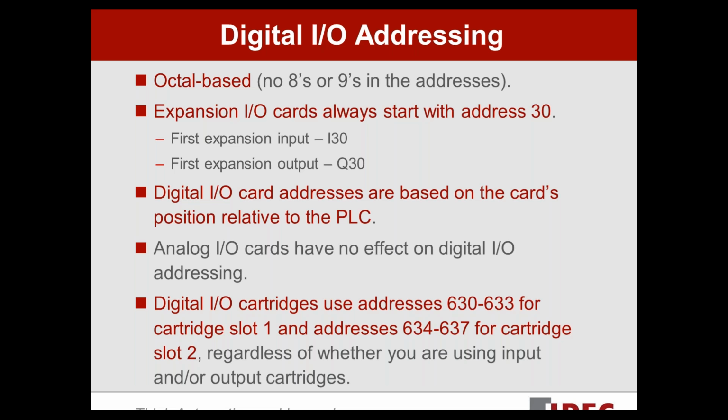So, if you've got an old Micro 1 out in the field that you need to upgrade, you can use an older version of WinLadder that supports the Micro 1 to grab the program. In that software, you can convert it to maybe an FC5A or even an FC6A PLC, save the file, open that file up in the newer version of WinLadder, and convert it to an FC6A without having to go in and remap all of your I/O. So it's pretty handy. But that's the method to the madness. That's why we did it.